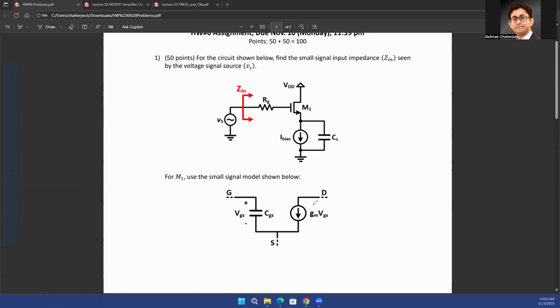So, okay, I didn't get the question. So what impedance you want to ground? Correct. No, current source is not a short. Voltage source is a short, right? So current source does not have, so there is no impedance associated with this ideal current source. Only if this is a non-ideal current source, you'll see a resistance in parallel to that.